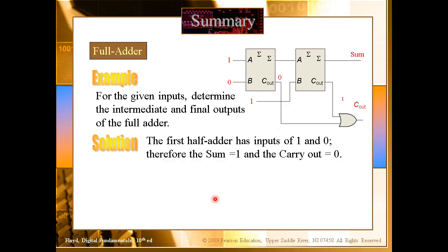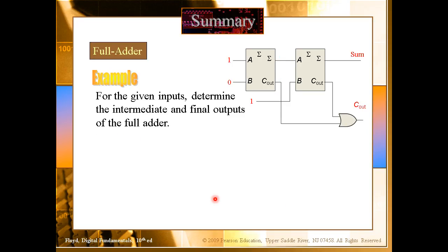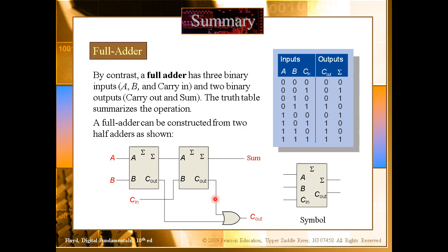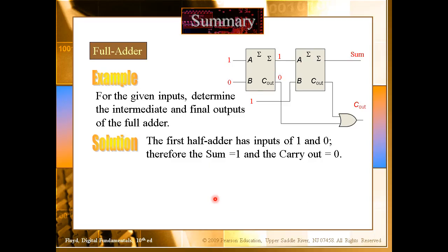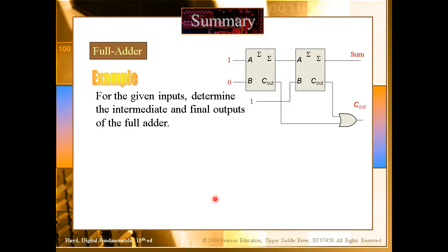Now, again, I tried to still draw the half adders so that we understand things a little bit better. In this case, I'm just trying to do a little bit of an experiment to show you how exactly it works for different inputs. So let's say this is a full adder, right? We are just showing 2 half adders and an additional OR gate. So let's see how it works. We have 2 inputs, A and B, and then this is a carry which is coming from the previous column, which is a 1. Now this is how exactly it should be working.